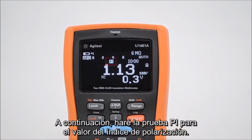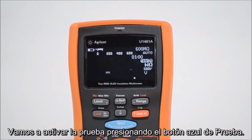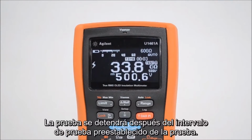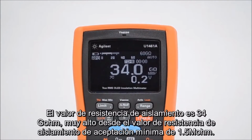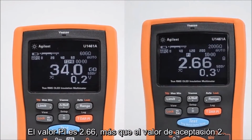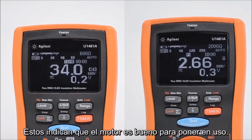Next, I will do the PI test for the polarization index value. Let's start the test by pressing the blue test button. The test will stop after the preset test interval. The insulation resistance value is 34 gigaohm, very high compared to the 1.5 megaohm minimum acceptable insulation resistance value. The PI value is 2.66, more than the acceptance value of 2. This indicates the motor is good to put into use.